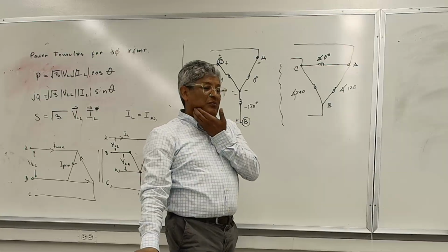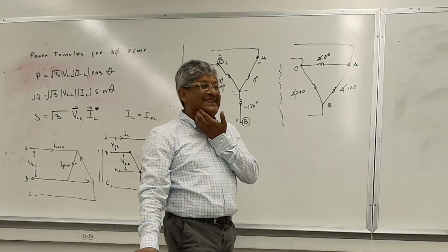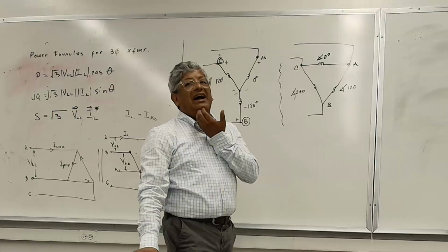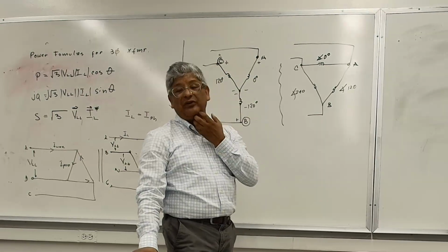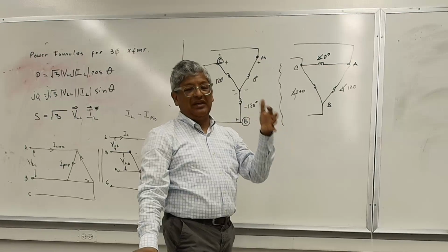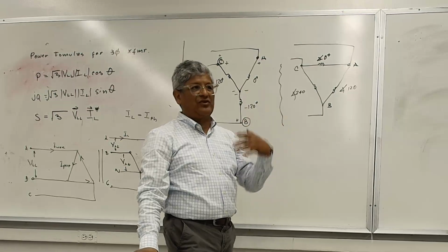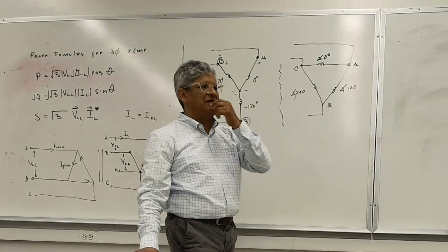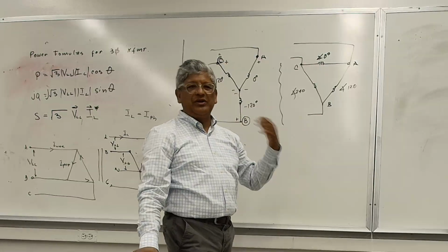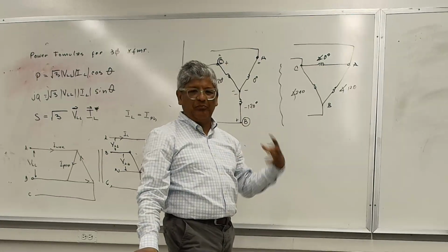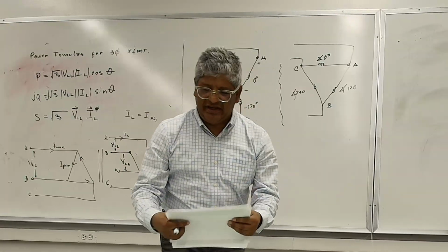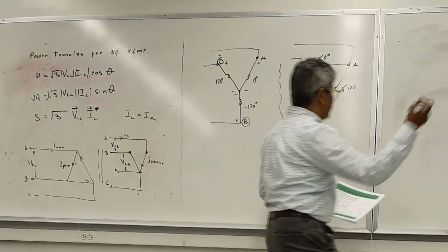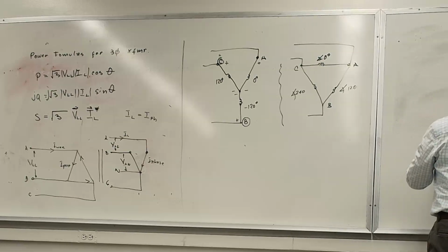Cal Poly Pomona, most likely for its buildings, requires a three-phase voltage source from the utility. So rather than using the single phase from the pole, they bring either a pad-mounted three-phase transformer somewhere outside the building, or they probably have three single-phase, pole-mounted transformers connected in either YY, delta-delta, whatever the application might be.